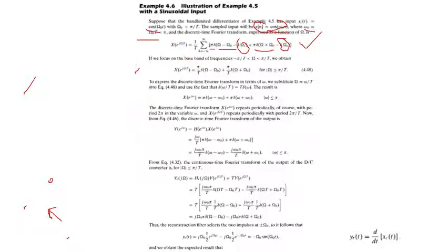So what we have done here so far, we have directly written the sampled form of cos in the frequency domain, and if we focus on the baseband frequencies, there is only the first copy that is at 0. So we just ignore this and we just ignore this. This summation will obviously be of no use when we are not using k. So this will be the spectrum. Okay, one will be at minus omega naught, this will be at omega naught, with the amplitude of pi by T.